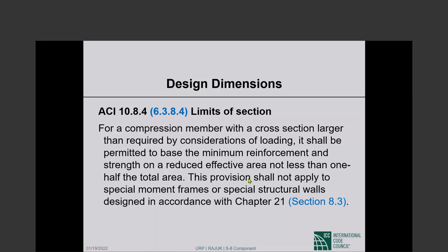I do not know if you realize formwork, which does not stay in place beyond 3 or 4 weeks, costs typically at least half the cost of a concrete structure. I don't mean the completed structure with glass and marble and bathrooms, no, but the structure itself, the skeleton before other things go in. The cost of the structure, half of that cost is in the formwork.